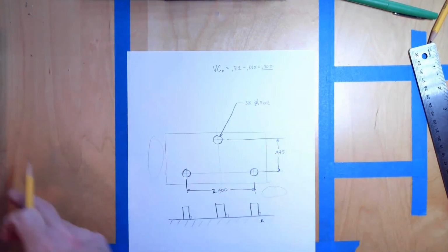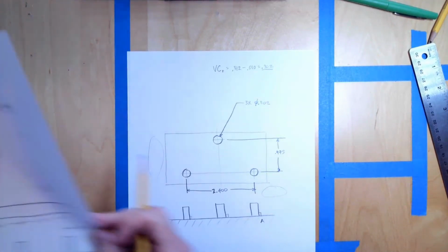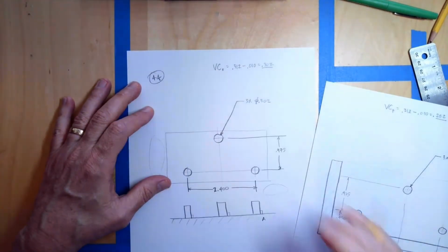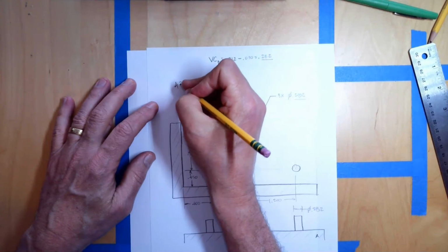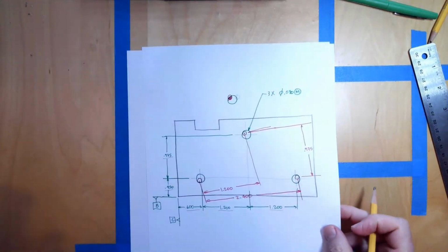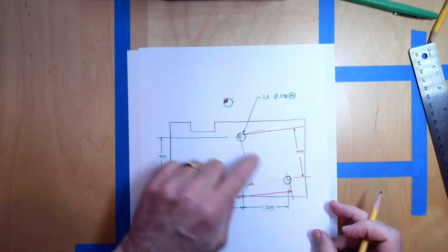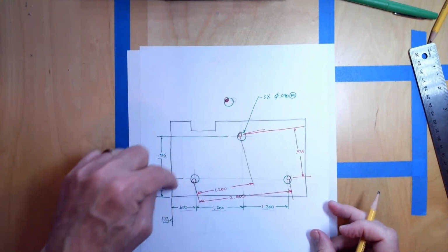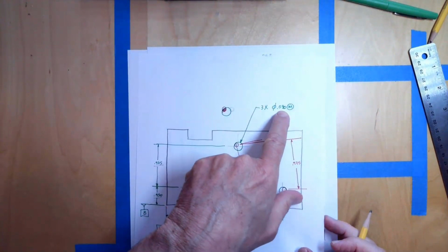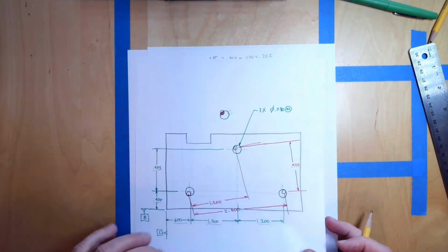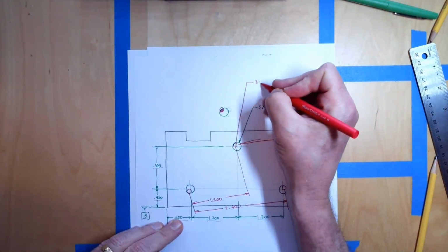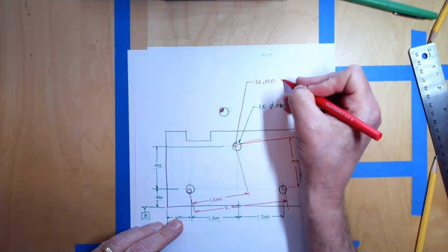Okay, so that is problem 42, 43, and 44. This is 44. This is 43. And then 42, remember, was this where we're representing the tolerance zones. Now, I kind of exaggerated these tolerance zones just so you could see clearly, right? But remember, the tolerance zones are given here, and the tolerance zone, actually, I left this out. The tolerance zone for this 3 times is 0.010 at MMC. Okay.